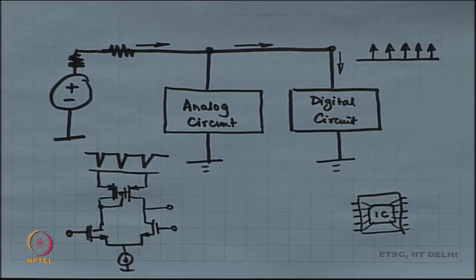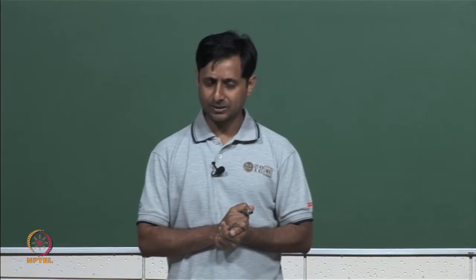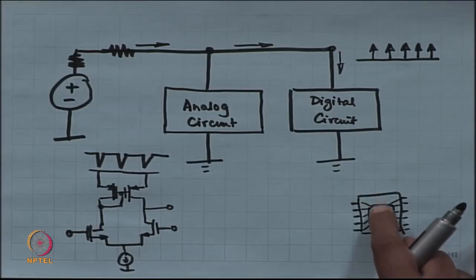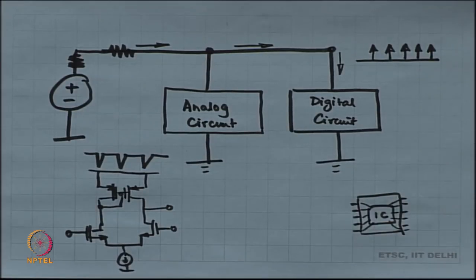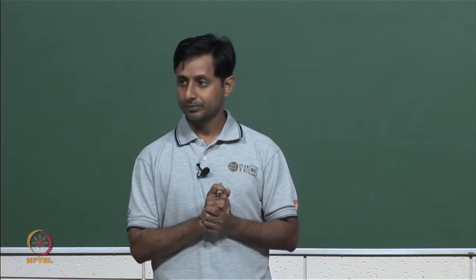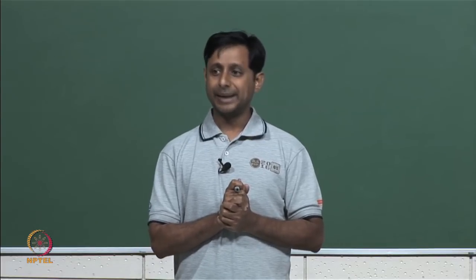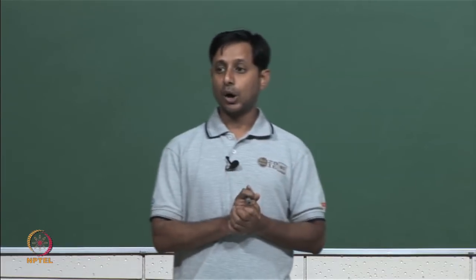They are made of gold because gold is the most malleable metal. You remember, ductile and malleable element, that is gold. So, typically these wires that connect the actual piece of silicon to the package are made up of gold. They are very thin, diameters could be as low as 0.025 millimeters. That could be the diameter, 25 micrometers, of that gold wire.